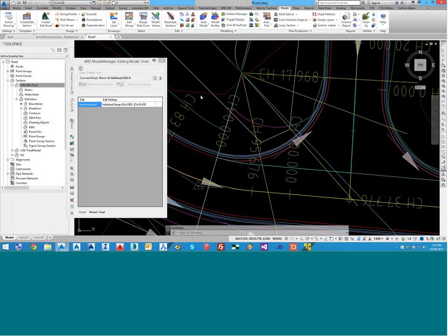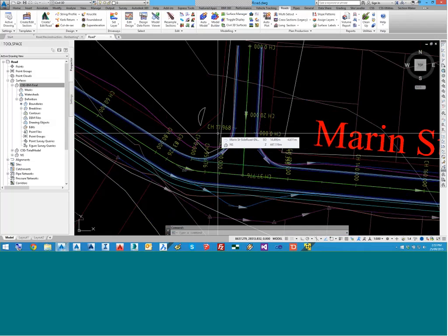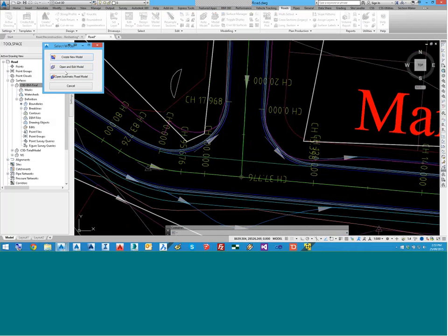So to recap on resolving these batter overlap issues, the first thing is that annoying message box that appears, and my answer to that is, hey, create a Model Builder model using automatic road model. It could just be basically a copy of the AutoModel. But as you're making changes to the software, that message box won't appear.